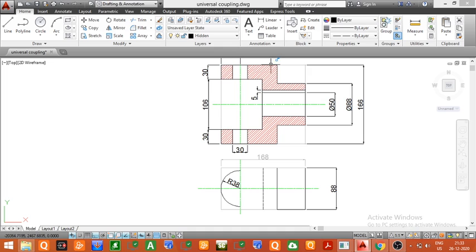That is, this surface comes first and then this surface comes. So this corner will not be visible from the top. So for this corner, after projecting in top view, we have to draw a dotted line. And finally we will join this point to the end by using a straight line, and again we will join this point to this point by drawing a straight line.